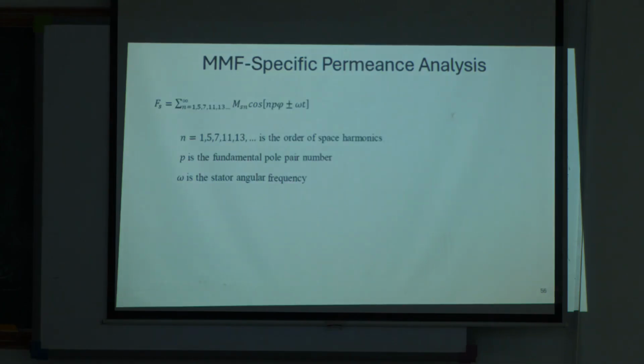So first thing is the stator MMF. Now stator MMF in electrical engineering, we always start with a very typical assumption that the winding is sinusoidally distributed, right? But we know for a fact that it is not true. We cannot manufacture such a machine, or it becomes very intense to manufacture such a machine. So when we actually use a practical three-phase stator winding, the winding distribution will result in what is known as space harmonics. How many of you have heard of space harmonics? Some of you have not.